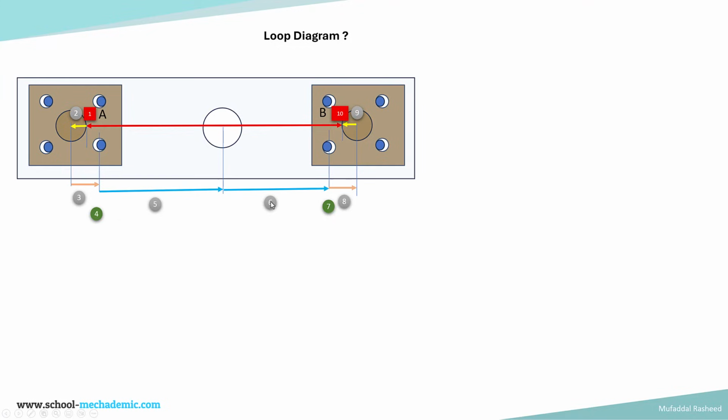Similarly, it's a mirror image on the other side. So the location of the pattern of the 4 holes with respect to center hole is specification number 6. Specification number 7 is again assembly shift. This post moved towards the right. So assembly shift again towards the right. This is moving towards the left. And then the specification of location of the post with respect to this hole. So the post location with respect to the pattern of holes is 8.